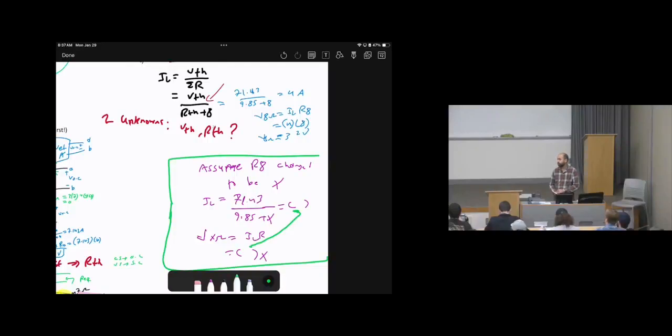Any questions? Again, the overall idea about Thevenin is to simplify the circuit. We have a constant part of the circuit, the existing system that does not change. Then we have the new or changed part. So the existing system will be replaced by an equivalent circuit, while the new system will remain. Then we can do several analyses on the new system. How about if we change this value? What will happen? Just substitute in these equations. How about if we do others? Substitute in this equation, and that's it. Okay, let's do another example.